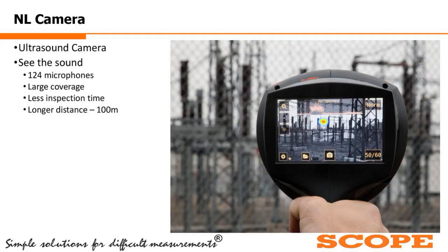It is once again an advancement of the ultrasound probes, which we used to use for a longer duration. Now multiple ultrasound probes are attached to a single product along with a visual camera, and software integration will give you the images as shown over here. This is the substation overall, and in this one near this city there is some problem, because here it has been highlighted with color, and what type of problem is also displayed on the top of this screen.